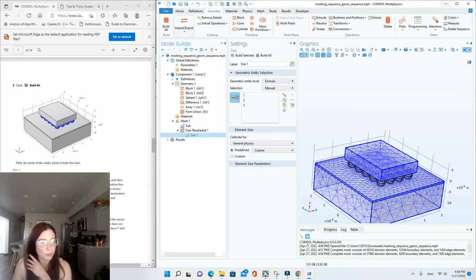The swept mesher operates on a 3D domain by first meshing a source face and then sweeping the resulting face mesh through the domain to an opposite destination face. For straight and circular sweep paths, you can use several connected faces as source faces. All faces that encompass a domain are classified as either source faces, a destination face, or linking faces. The linking faces are the faces connecting the source and destination faces.